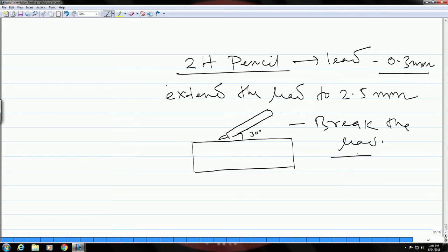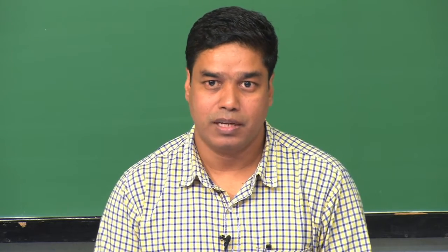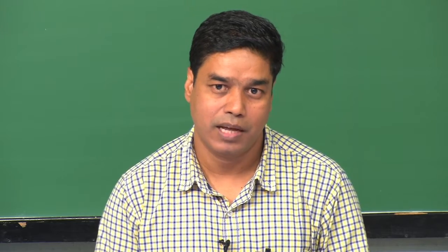When the lead is broken, suddenly it will release a lot of stresses, and that will be released onto this surface, which will generate a lot of vibrations in the atoms at the surface, and that is how this acoustic emission will be created. And since it is coming out from a fracture phenomenon, this will be very close to actual acoustic emission events happening inside a component due to a damage. So, this is how they came up with this method, which is very simple yet very effective to simulate and calibrate acoustic emission systems.